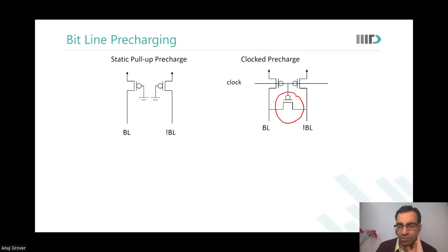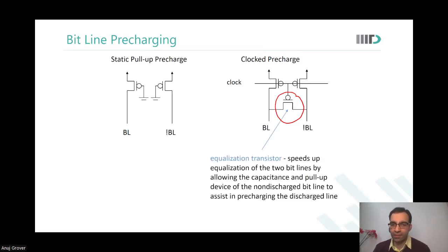So after every clock cycle, it will set them at the same voltage level. Okay. So this additional PMOS is called an equalizer. That is really the primary function of the equalizer. It ensures that both the bitline and bitline bar are precharged at the same level. So if you had read a 0 earlier and now you want to read a 1, the other bitline has to discharge. If they were already equalized, just the discharge has to happen.